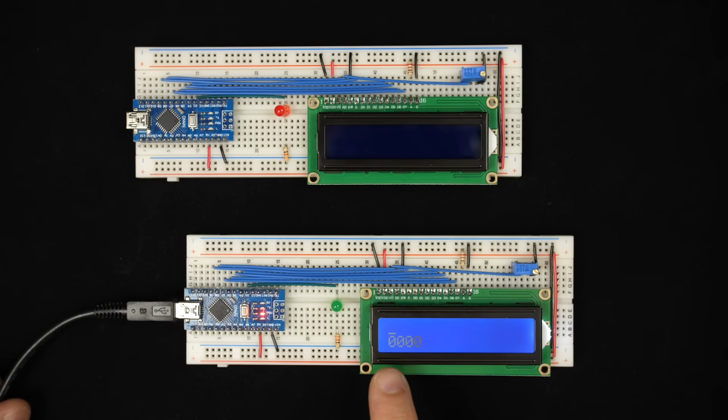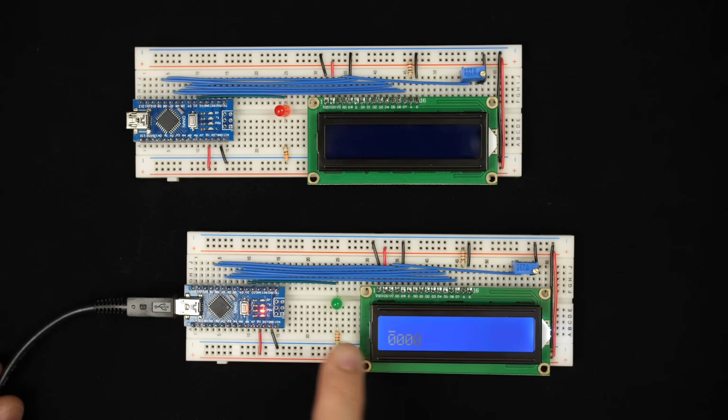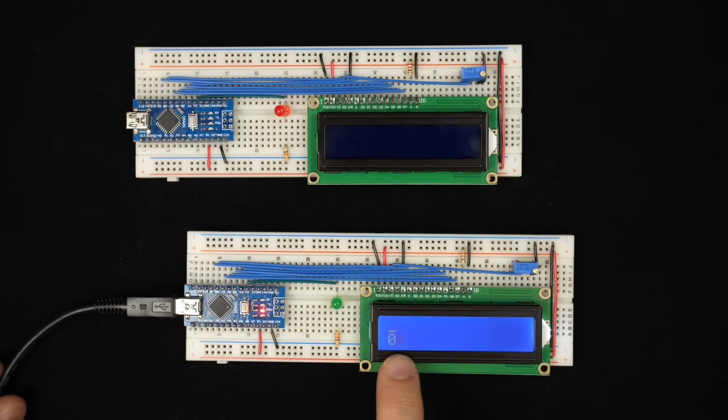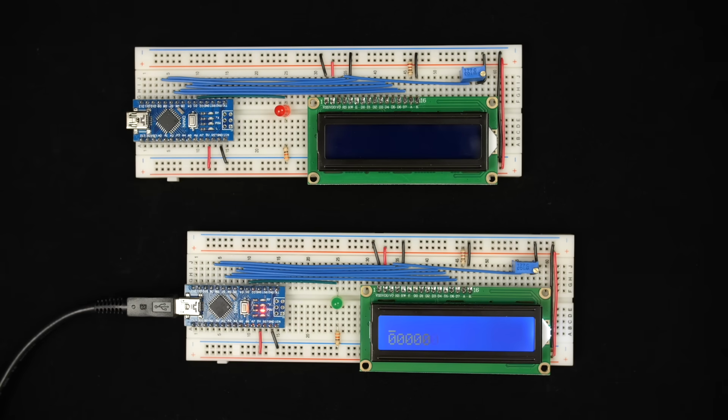And there it goes. And you can see it's just printing zeros, which makes sense, right? Because this is our input and our input is just low. So it's looking at that every 200 milliseconds, and every 200 milliseconds it's low. So it reads in a 0. So we're just getting a bunch of zeros. So now let's hook it up to our transmitter and send it some data and see if we can get it to receive that correctly.